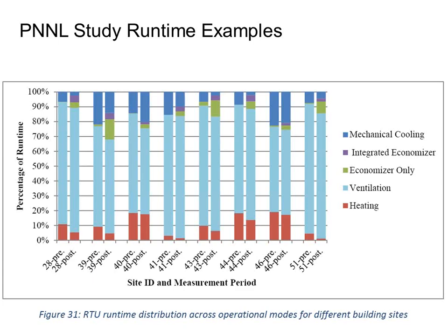Ventilation mode is the dominant mode, which is why when we start talking about things that save energy, like improving the refrigeration system, or if we somehow started installing 95% gas efficient rooftop units, that would be great, and we'd all love it. But compared to ventilation hours, it's kind of irrelevant. So there's a lot of ventilation hours, which is basically fan energy. So you can see why picking on the fans has the biggest payback scenario of all these things that we're going to discuss.